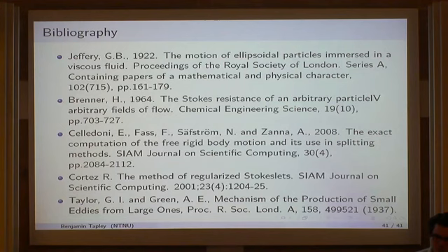But is that correct? I'm not so connected with the engineering side. It's important to localize. When you have these spectral element solvers, you have all these polynomials within the cell, and they're defined globally. So why can't you just keep them and not even worry about an interpolation algorithm? The reason you don't is that it takes up way too much memory, and the computers can't really handle that.